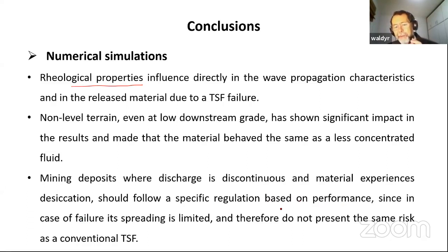Minor deposits where discharge is discontinuous and material experiences desiccation should follow specific regulation based on performance. That's a problem we have in Brazil, because in our dambreak analysis these days, they say that you must consider 100% of your reservoir volume involved in the flow process. And we have proved that in the case of Daniel's case, it was just 9% or maybe 40%, but not 100%.